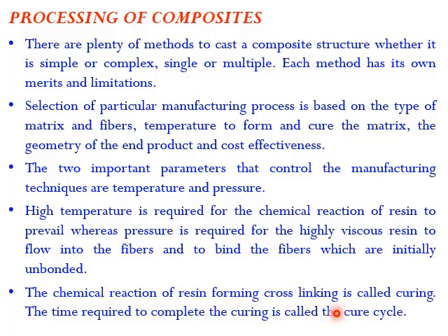The chemical reaction of a resin forming cross links is called curing. The time required to complete the curing is called the cure time. If you use thermosets, the curing time may require a little bit more. If we have the same thing with a thermoplastic, the curing time and the temperature which we require may be less. Depending on their curing time and curing cycle, one has to choose what type of processing method to use for a composite material.